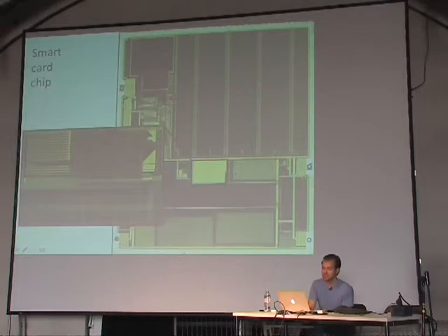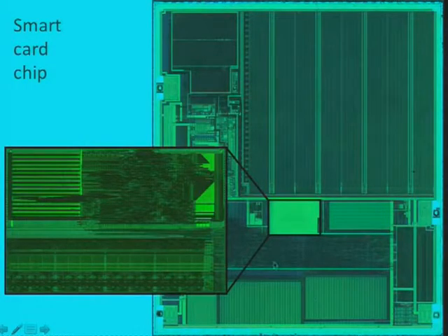The chip area is dominated, though, by memories. Up here, there's flash or EEPROM. So this is read-write memory. Down here are 2 banks of ROM. So that's once writable, basically through manufacturing. The program code, the operating system, some application code is written to these, and it's not changeable throughout the lifetime of this card. So no possibility for patch management should anybody find software bugs in here.